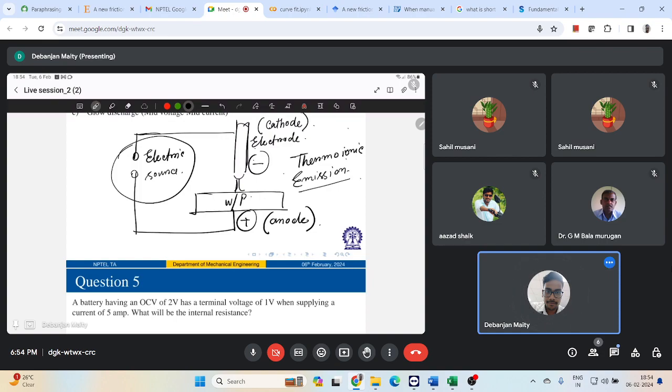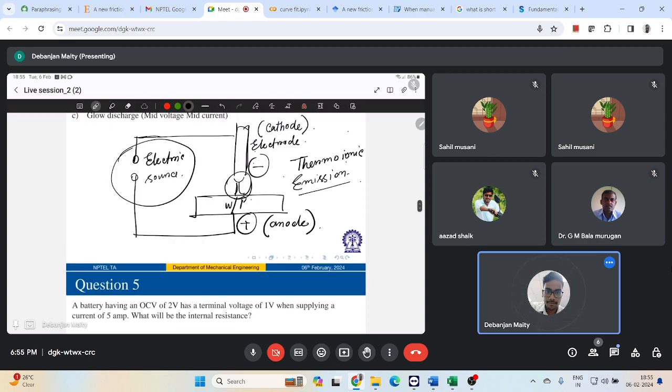Initially you have to provide a good contact between the electrode and workpiece. Whenever you do welding, you first make good contact, and thereafter the electrode is withdrawn. As a result, the metallic bridge generated by that contact starts to break, which increases the current density per bridge.